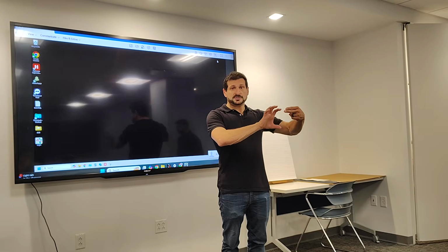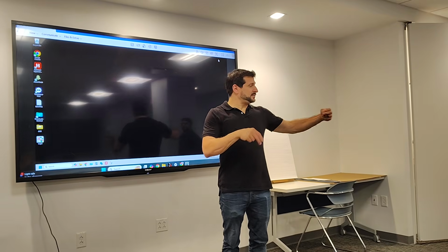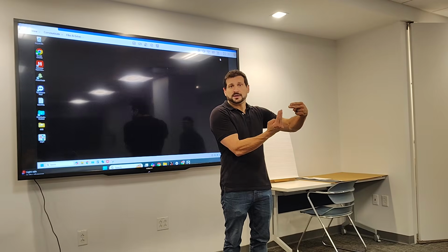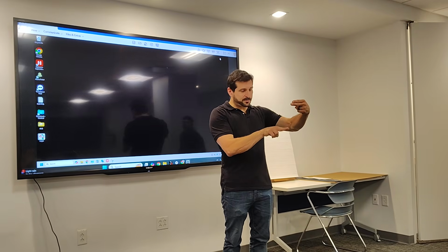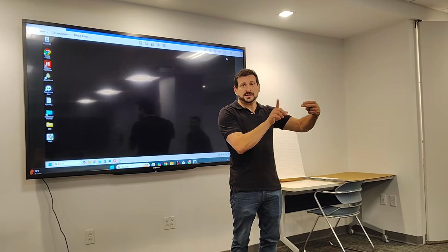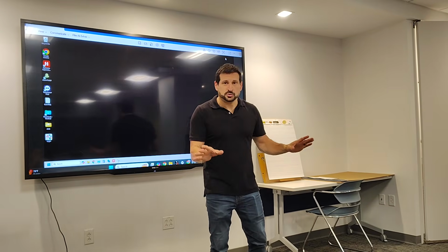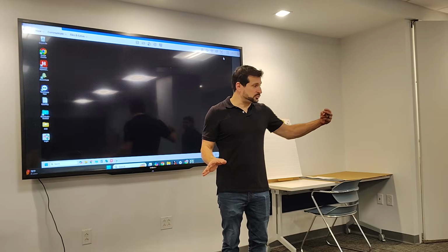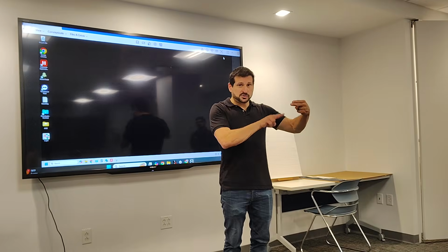The virtual points, those we change. My space temperature is 78. My set point is 78. We're good. But I don't want it 78. Change the set point to 76. Now all of a sudden it says, hey, I'm 2 degrees hotter than I want to be. I've got to cool down, right? So the first thing we have to know is what points we're allowed to touch. Don't touch inputs. Yes, change virtual points.